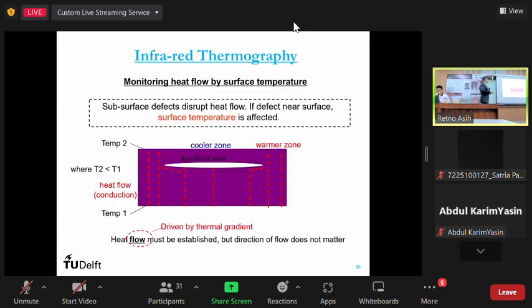Right? So this is infrared thermography. You have a change of the color map, a heat color map change because of the defect, for example, that you have near the surface, and you use that mapping for detecting the structural health state.